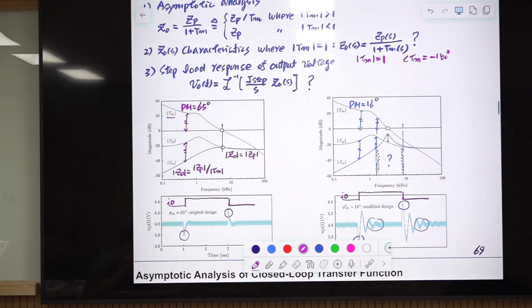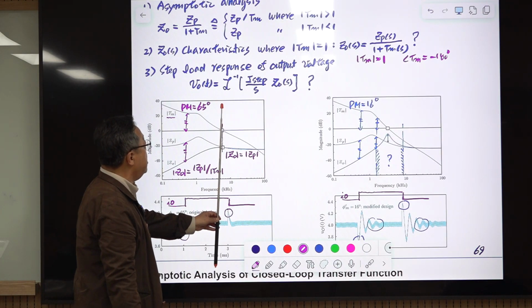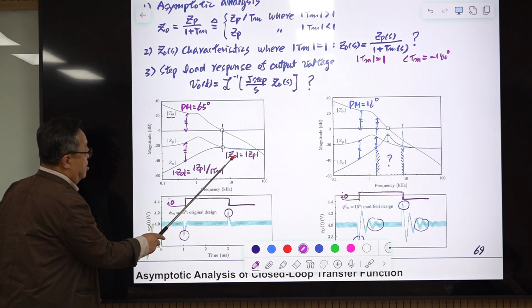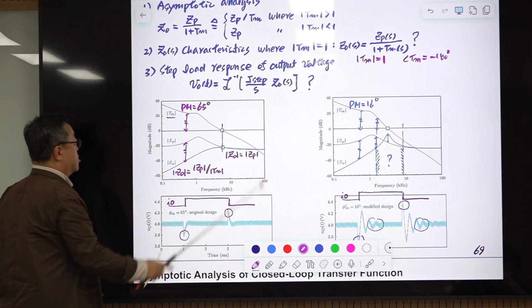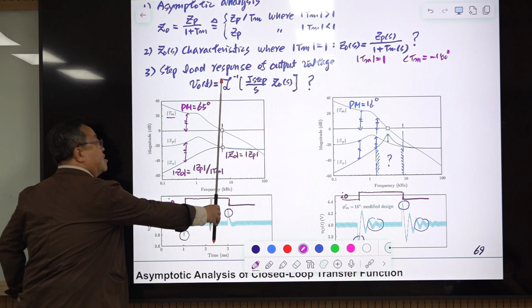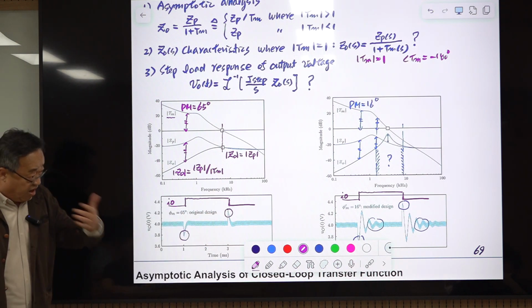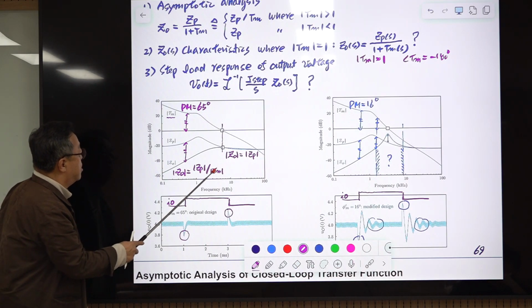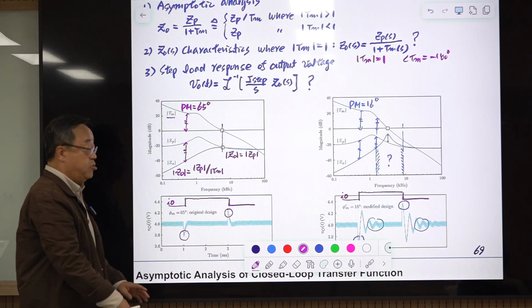The borderline of this analysis is the loop gain crossover frequency. After this frequency, the magnitude curve of output impedance is just a copy of the open loop load current to output transfer function. Below these frequencies, where the magnitude of loop gain is larger than unity, you have this rule. This is a division in linear scale, but in log scale there is a subtraction of magnitude, so you have a subtraction rule.